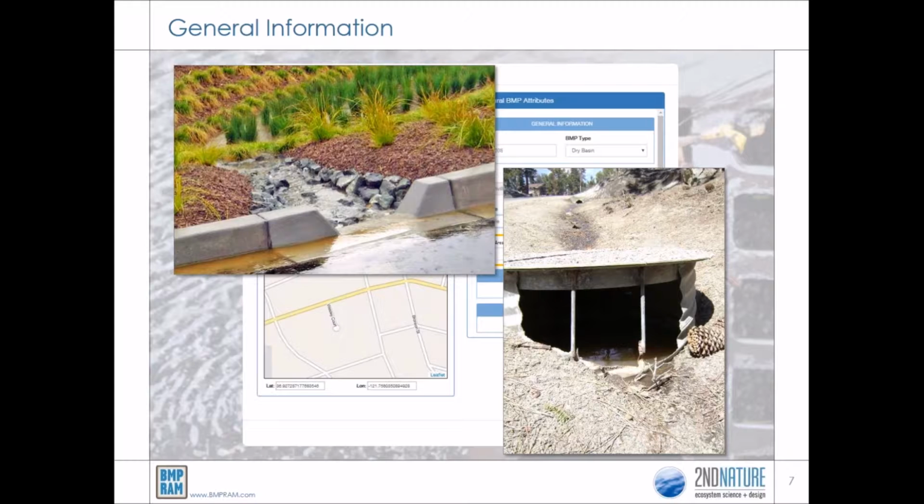The user can use a hard copy Google Earth image or a mobile GPS application to drop a few location pins and designate the drainage area boundary. Once the area is reasonably delineated, the user can choose to return to the office and use Google Earth or another program to draw the area and obtain the acreage. The other option is to complete a reasonable field sketch of the area and use a survey tape or survey wheel to measure dimensions.